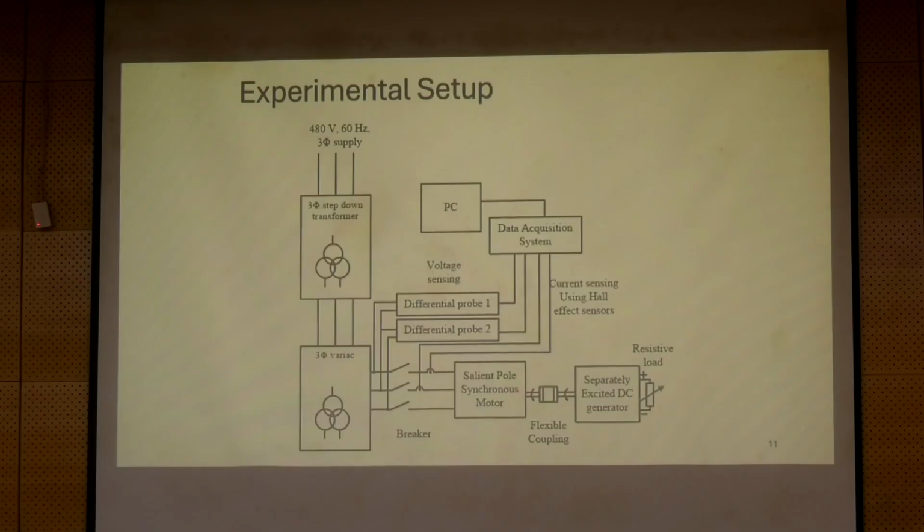Especially if you recollect the MMF permeance analysis, we found out that there are sideband frequencies. So if you have 50 hertz, you get 75 hertz and 25 hertz. So the 75 hertz is greater than 50 hertz. So that should be used as your frequency of interest if you are trying to capture it. Okay, so you may have to capture based on those kinds of higher frequencies.